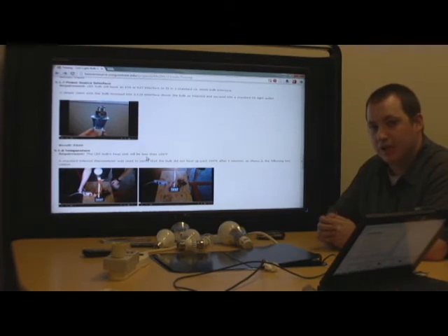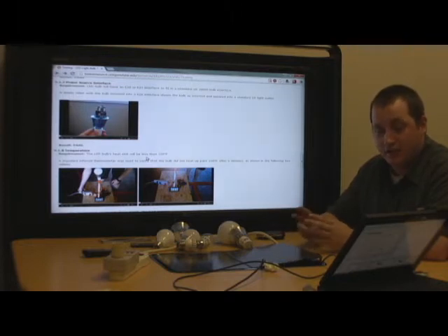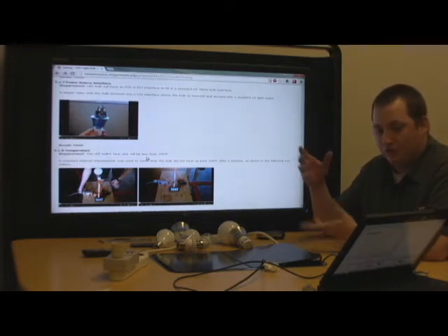Our next test was the interface check. We wanted to make sure our bulb screwed into a standard E26 or E27 socket. For this we did two things. First, we measured it: the E26 standard is 26 millimeters in diameter, and ours measured 25.9 millimeters, so it met that spec. Also, to make sure it was securely in the socket, we shook it at a rate of about 2 hertz to make sure it wouldn't fall out of the socket.